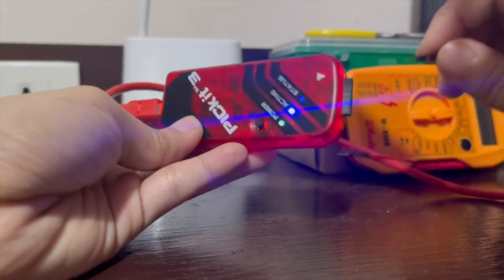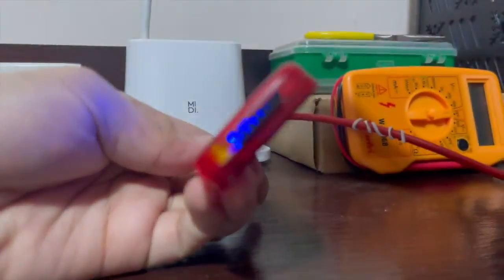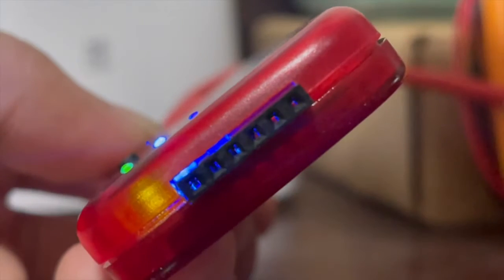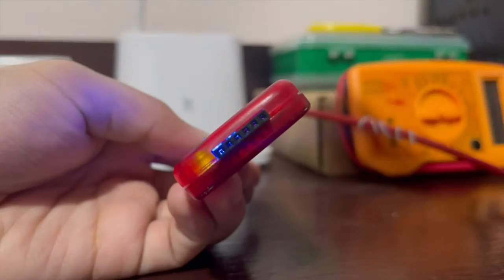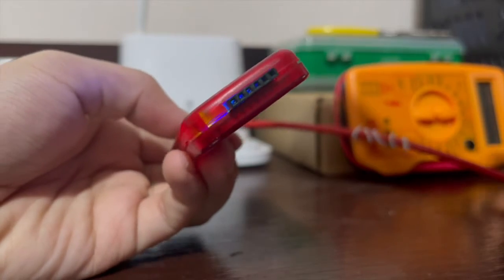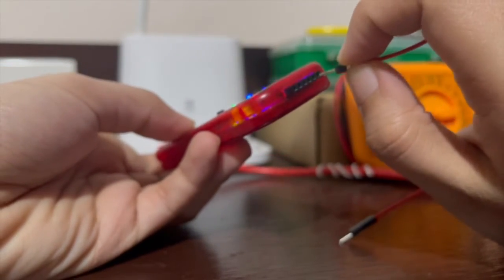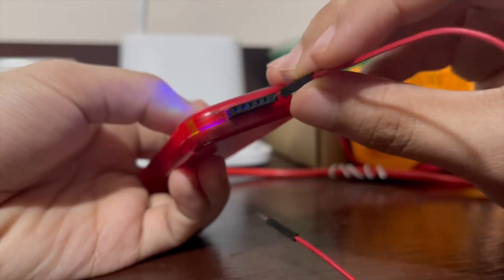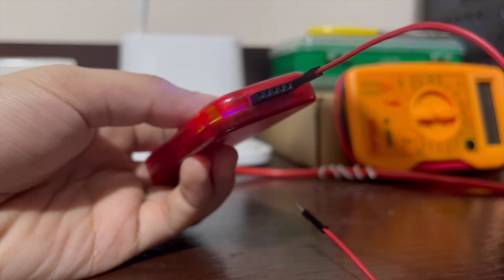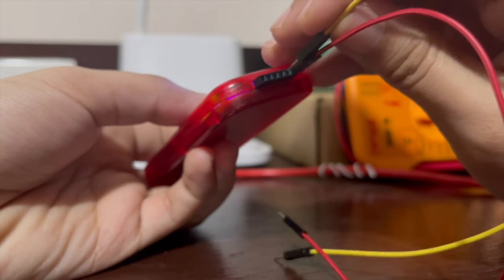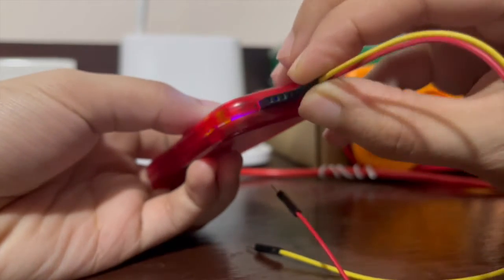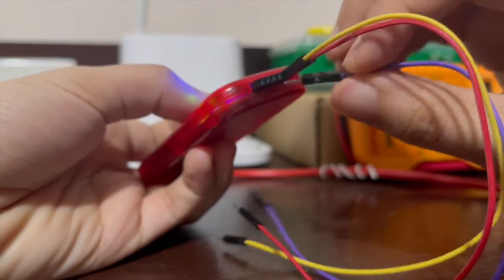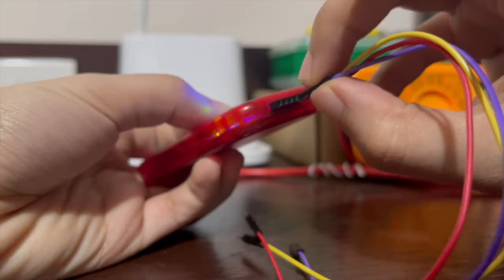And now, if we are to connect the pins in our PICkit, as you can see, there are 6 pins that can be inserted here. So the first pin is the MCLR or VPP, and it goes here. And then the second pin is the VDD target. The third pin is the VSS or the ground here.